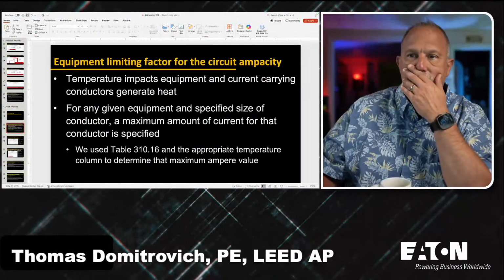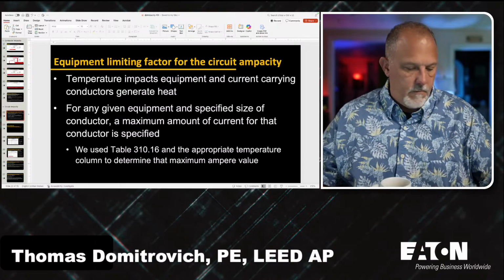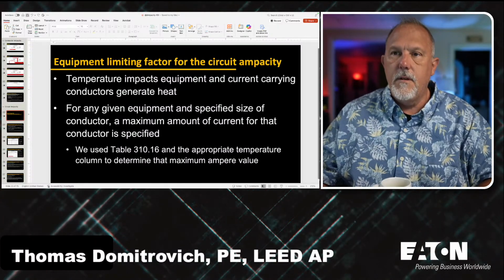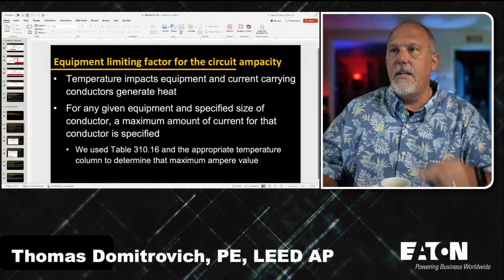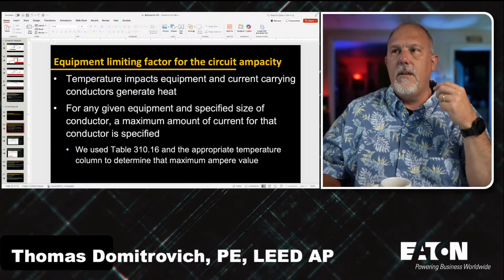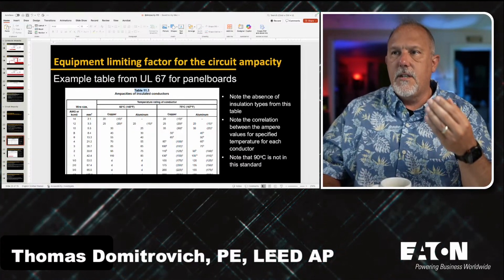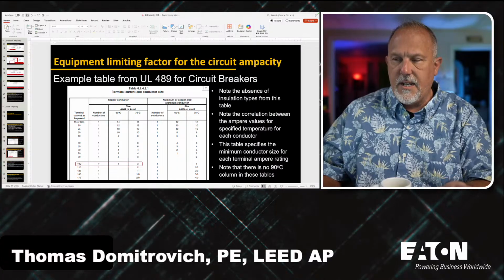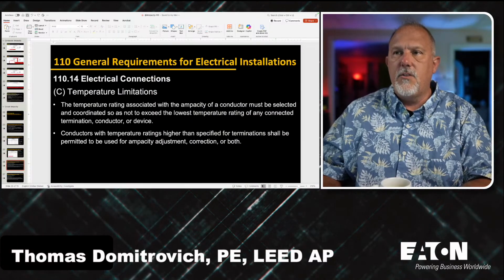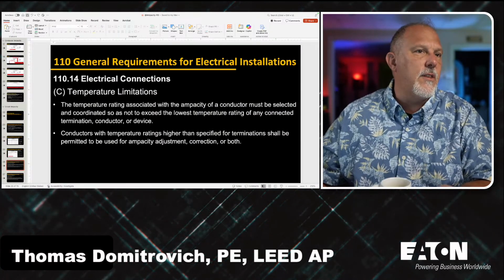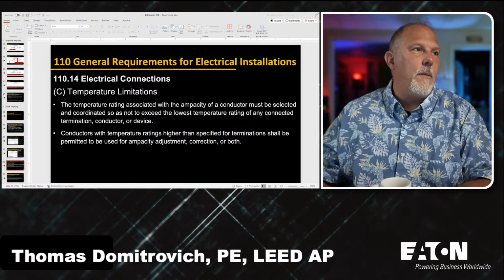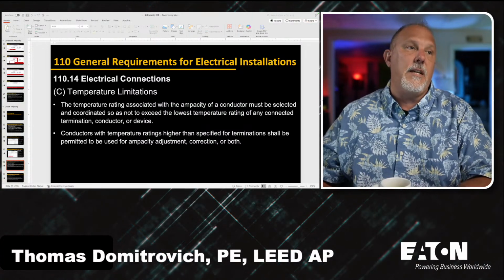if we go back to this, Control Z. I got my circuit ampacity. I got my temperature impacts the equipment. There's examples from 2 different standards. Then we get into 110.14 and what I was thinking of. So in the parent text of 110.14,